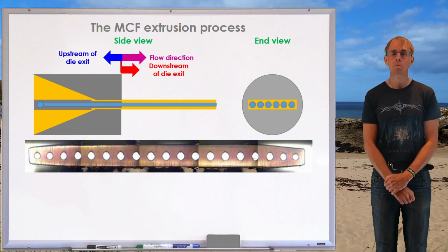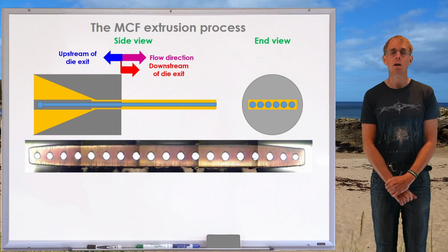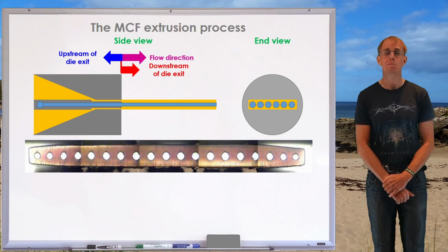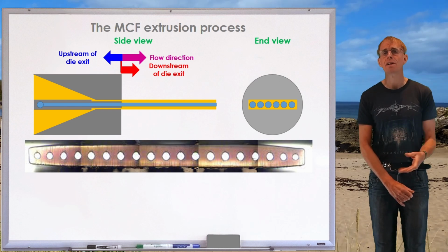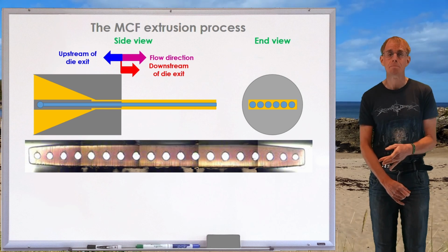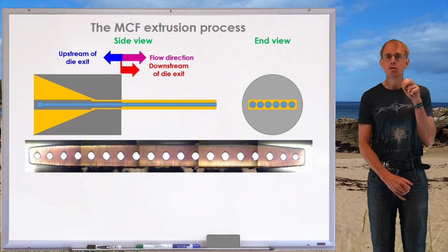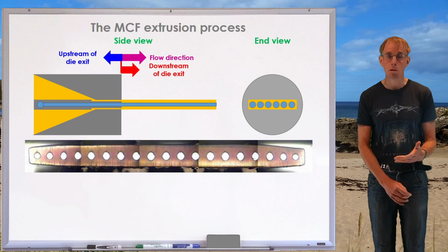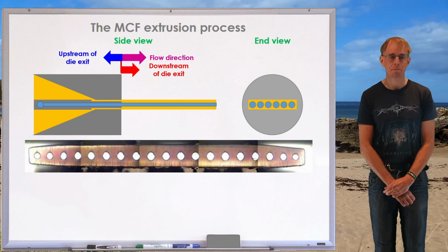In this particular example, the width of this product is about 6 millimeters. There are, I think, 19 holes in this particular product, and each hole is around 200-250 microns in diameter. And so we were looking to innovate a process that took the guesswork out of foaming, the nucleation part being the guesswork. So what we were doing was strategically introducing voids within a polymer in order to change its properties. And this was the method that we'd innovated to do that.